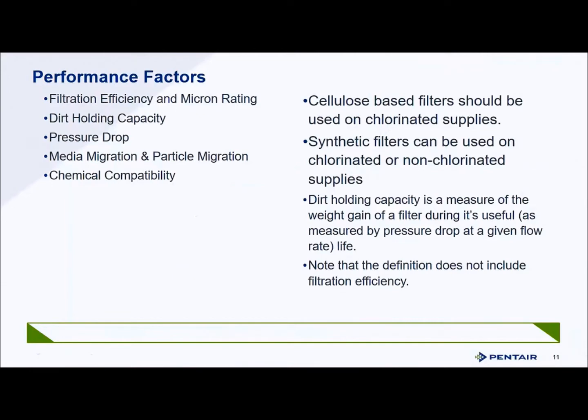So you get the already retained dirt in a filter puffing and sort of breathing a little bit and reorganizing inside the filter. How often it does that, and how much you're able to reorganize that dirt in a way that allows for greater flow, will impact the life of the filter. It's a lot more complex than throwing carbon in a can.